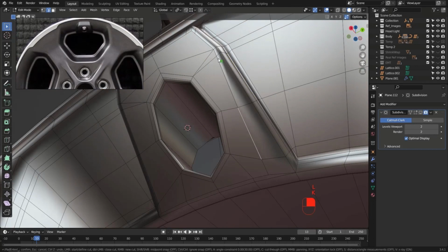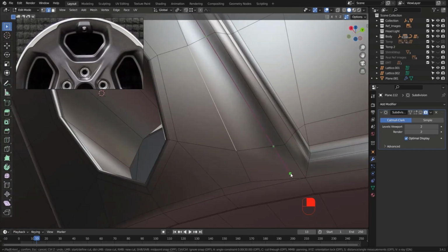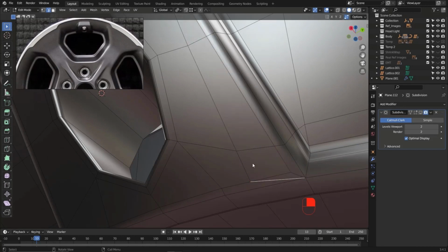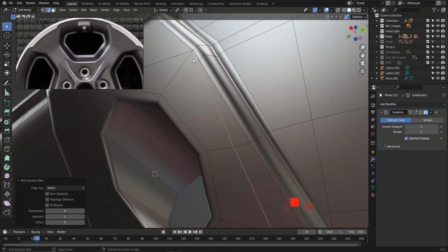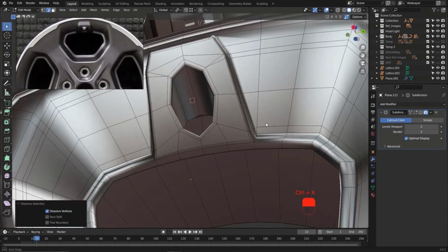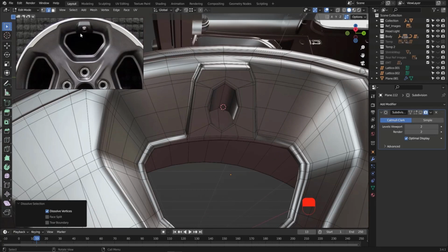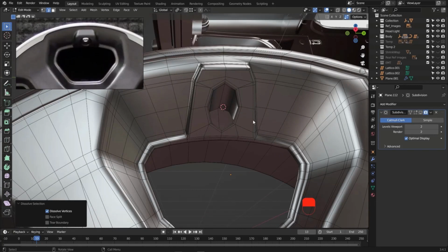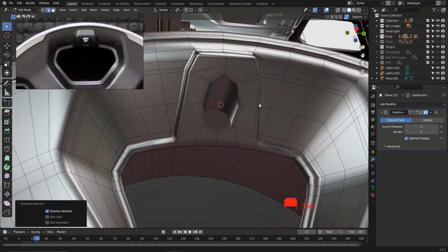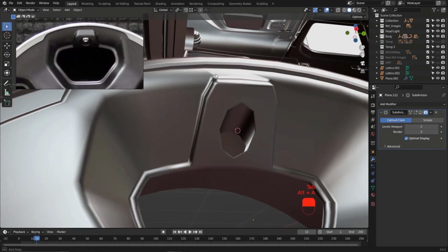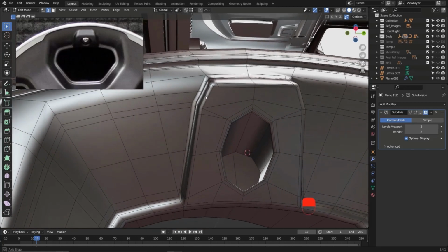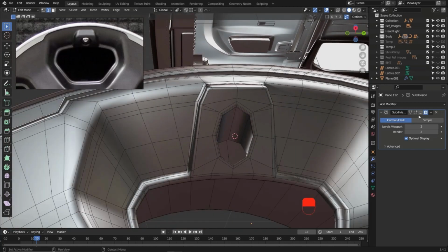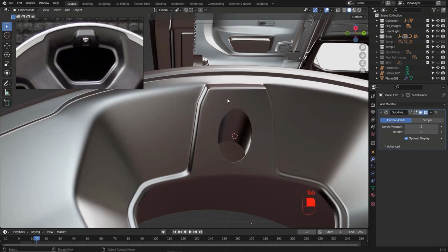Use the knife tool and let's create this edge and delete this one. We don't need it anymore. Now we will have something even closer to this result. Let's tab again. Let's see if we forgot anything else. Activate subdivision surface, tab.